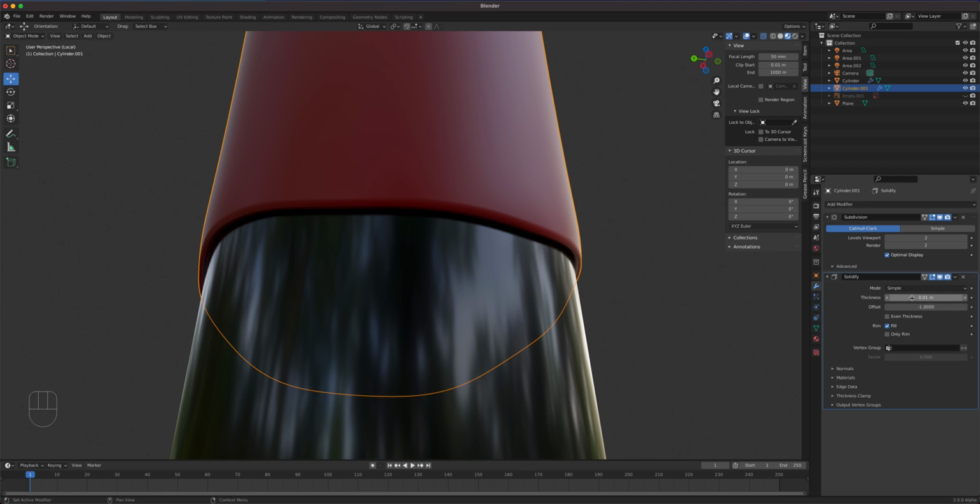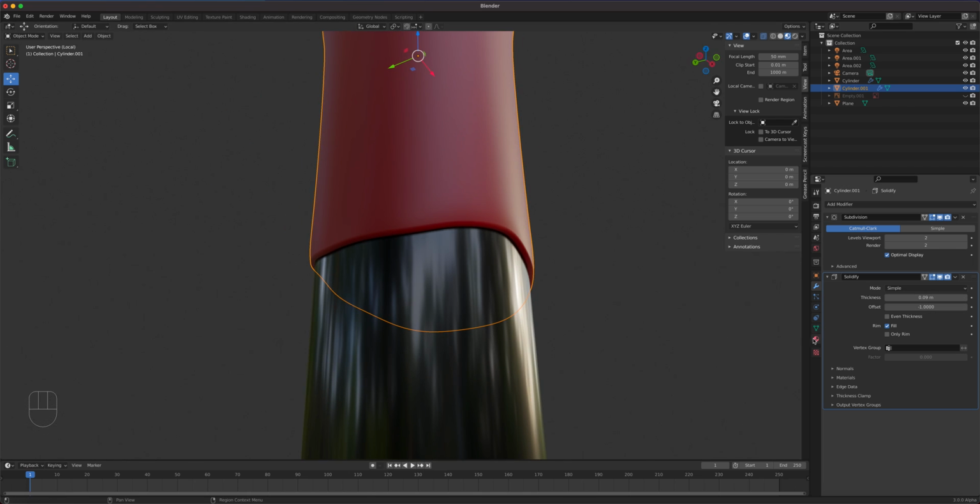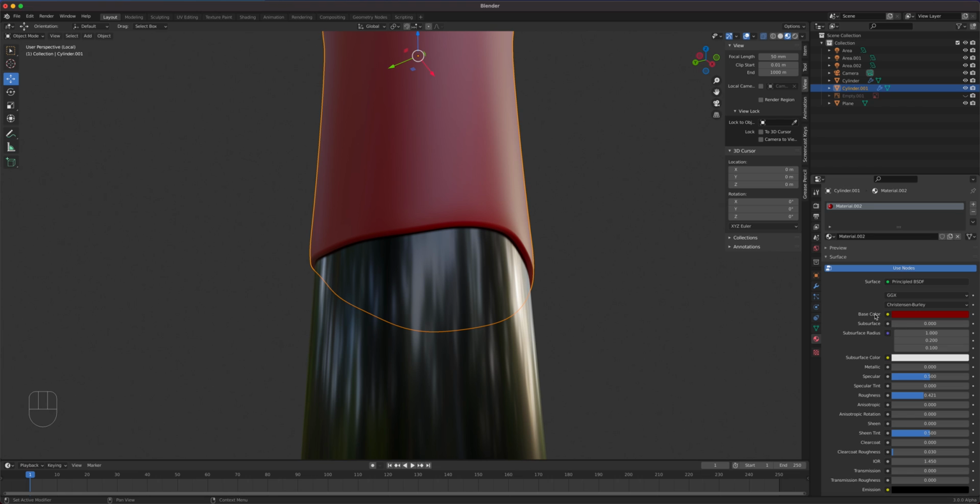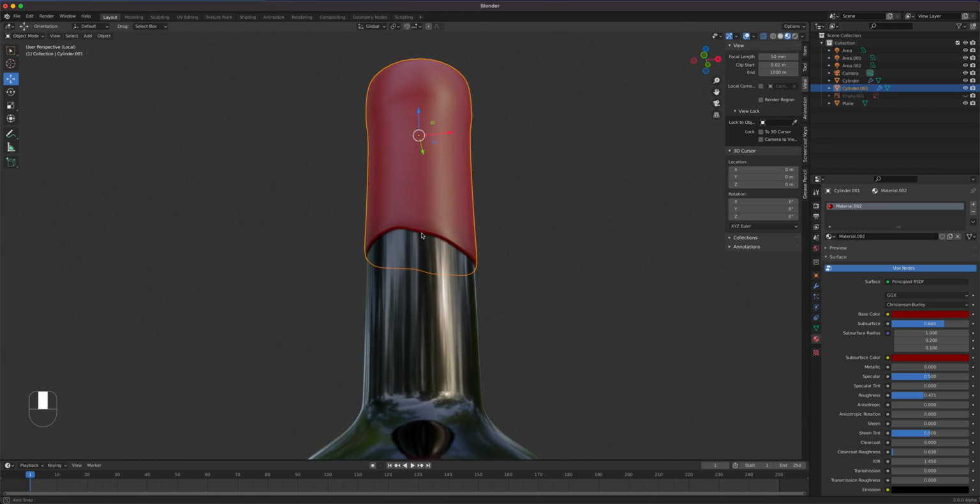And you can increase that thickness going in or out. Okay, so I think with that setup, it's probably good right there. I put 0.9. Another thing we can do is give it a subsurface value right here. Okay, so it's making it kind of translucent a little bit. If I click and drag the base color to the subsurface color and then just give it that value, it's making it a little bit translucent, more waxy in a way.